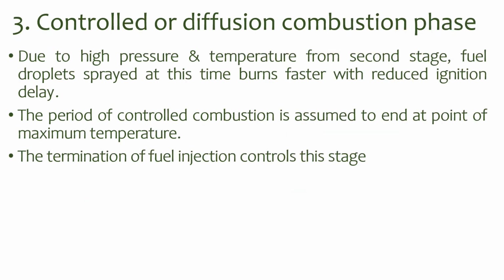The third stage is called controlled or diffusion combustion phase. Due to the high pressure and temperature from the second stage, fuel droplets sprayed at this time burn faster with reduced ignition delay. The period of controlled combustion is assumed to end at the point of maximum temperature. The termination of fuel injection controls this stage.